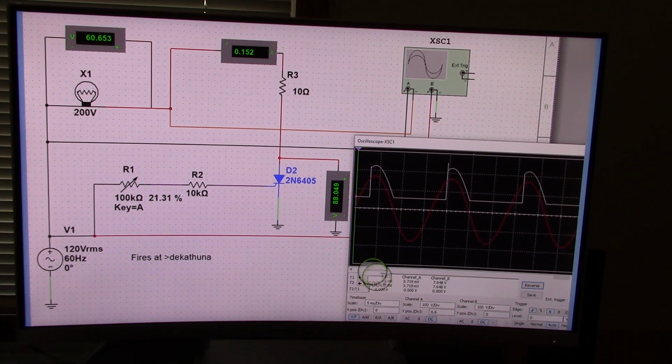You also remember that by adjusting these cursors back and forth, you can measure the voltage that this is reading. If you're talking about this, this is channel A, which is the orange and black color line. So if you move this, that'll be this channel here.